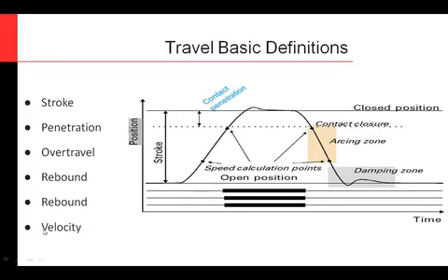One other thing, when you're dealing with velocity, you need to measure it in a certain range according to these speed calculation points. Generally, you want to put these somewhere in the arcing zone. You really care what's going on when that interrupter is interrupting the arc. And you want kind of a straight line there, a nice linear portion of the curve to measure on. And I'll talk about speed calculation points in just a minute or two.